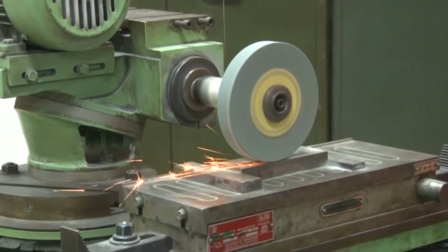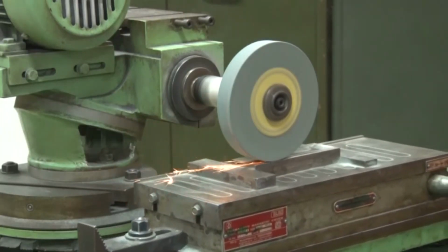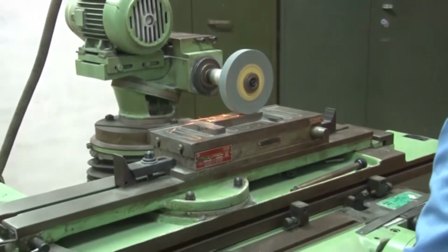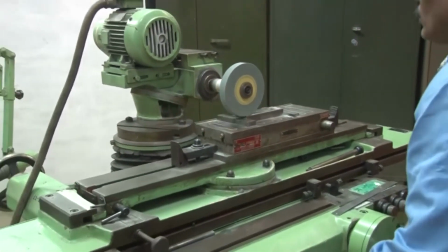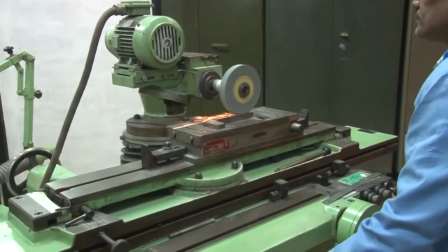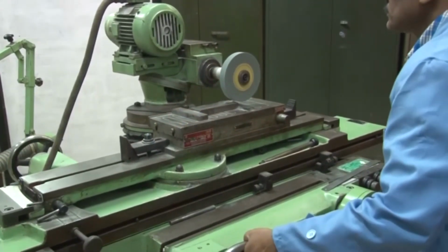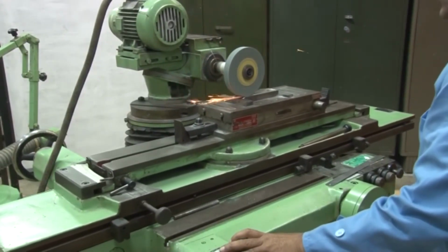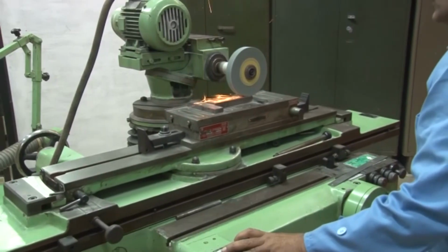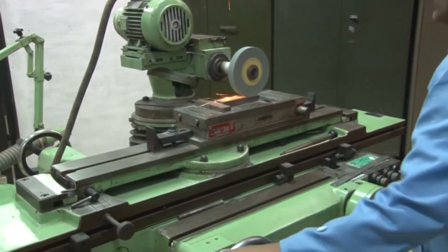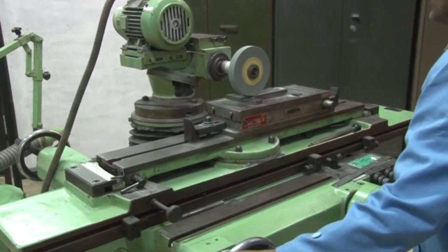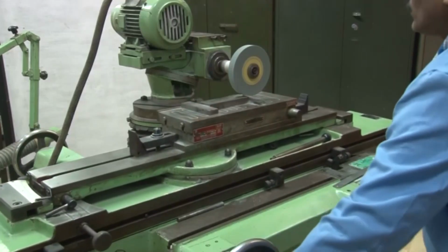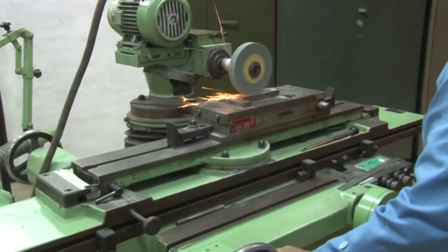That means, in the longitudinal direction you are having the reciprocation, and in the cross feed, that is perpendicular to the longitudinal feed, you have to have the feed to get the entire width covered. So, pass by pass, the entire surface will be ground. In each pass, one segment of the width is being ground, and when the cross feed is given, finally the entire width and the entire surface will be ground.